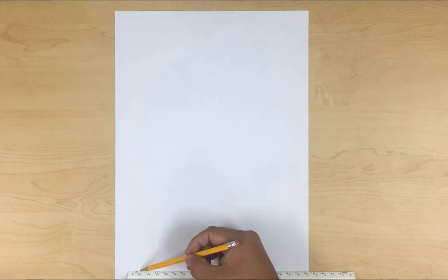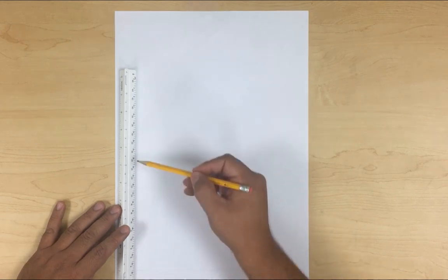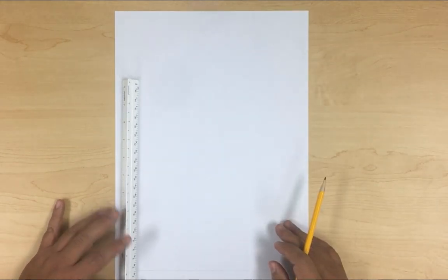That is 64 feet, and I'm going to try to center it on my sheet. In this case, 0 is here, 64 is right here. I'm going to have it as straight as I can and leave the same space on the sides, and draw a very light line right here. Okay, so it's 64 feet. Now the depth of the lot is 95 feet. For this one, our scale only goes up to 93, but just to make it easier, I'm going to do a line that is 80, and then we'll do the 15.